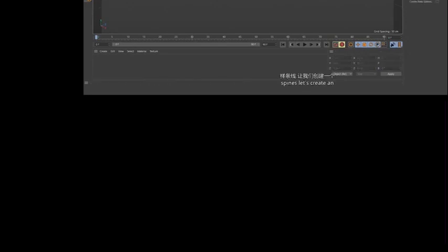Volume Builder also works with splines. Let's create an object. By adding it into the generator, we get a 3D model. If I reduce the voxel, we can see that spheres are created along the splines. Their settings are accessible here. We can change the size of the spheres and adjust their density. As well as for regular objects, we can add anti-aliasing to them.